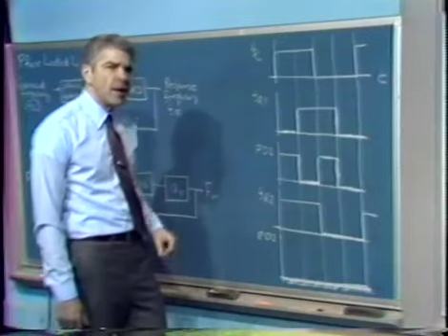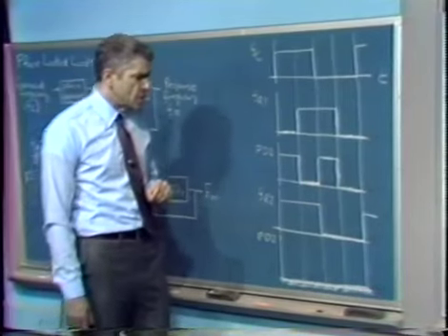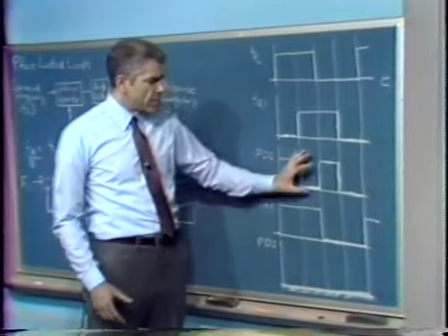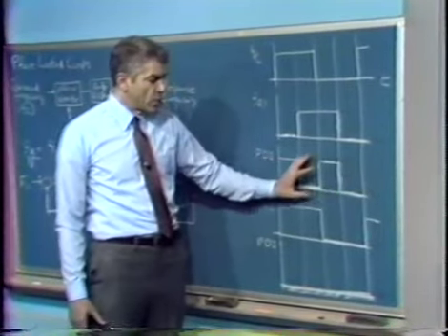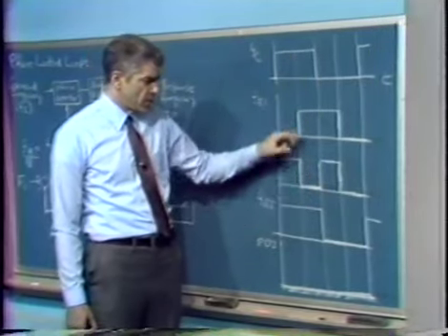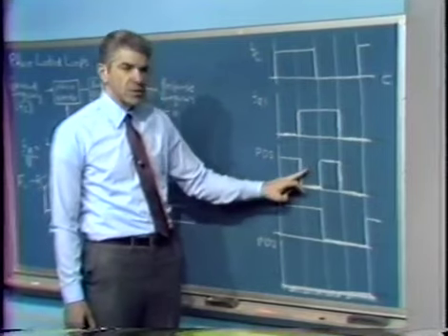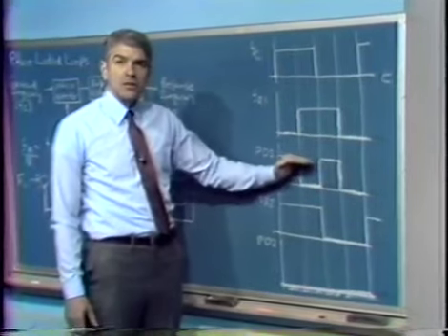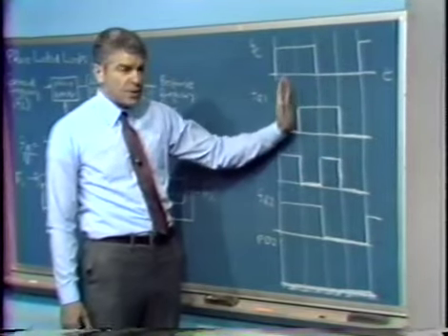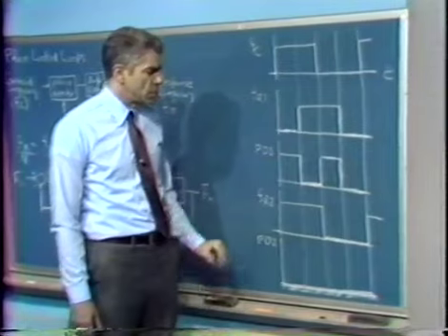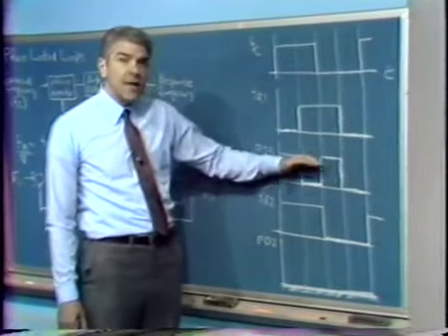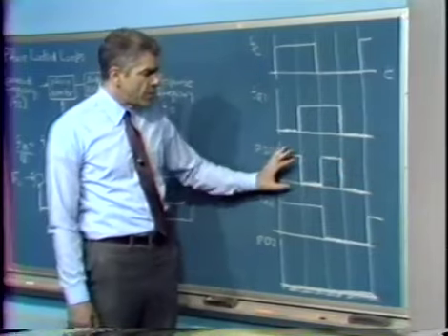Again, I think you notice the same sort of thing as we had in one of the oscillator examples before, where we have a high-frequency process going on. The exclusive OR gate, in this case, is running at twice the operating frequency of the loop for this particular combination of inputs. The output is a double frequency component, plus a low frequency, in this case a DC component, if there's no change in the relative phase between the two signals. What we're interested in, the information, is contained in the average value of the signal. So we have to apply some filtering.